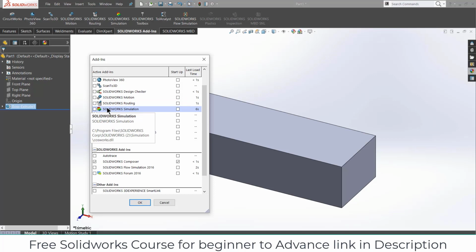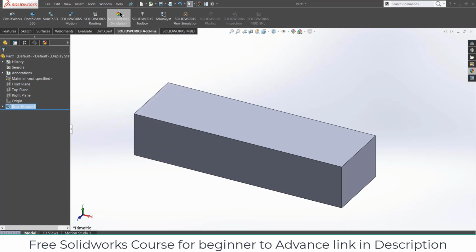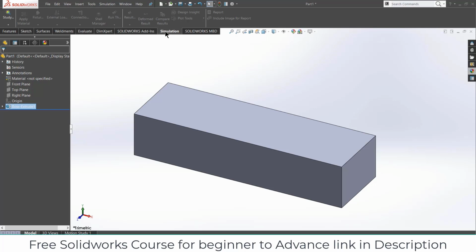Just in case it is not visible in your SolidWorks, it means that you haven't installed it, so you need to reinstall your SolidWorks with SolidWorks simulation. So close this and click on SolidWorks simulation. When you click on it, wait a little time and a simulation tab will pop up. Click on it. When you first see it, all these options are basically blocked. You are not able to use them.